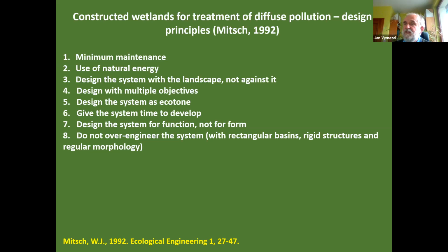We should give the system time to develop. That means that we should not expect immediately a very high performance, even though wetlands usually do so quite early. It should be designed for function, not for form, and they should not be over-engineered. So that means that it should be really fitting in the landscape and not using rectangular bases or some concrete structures and so on.